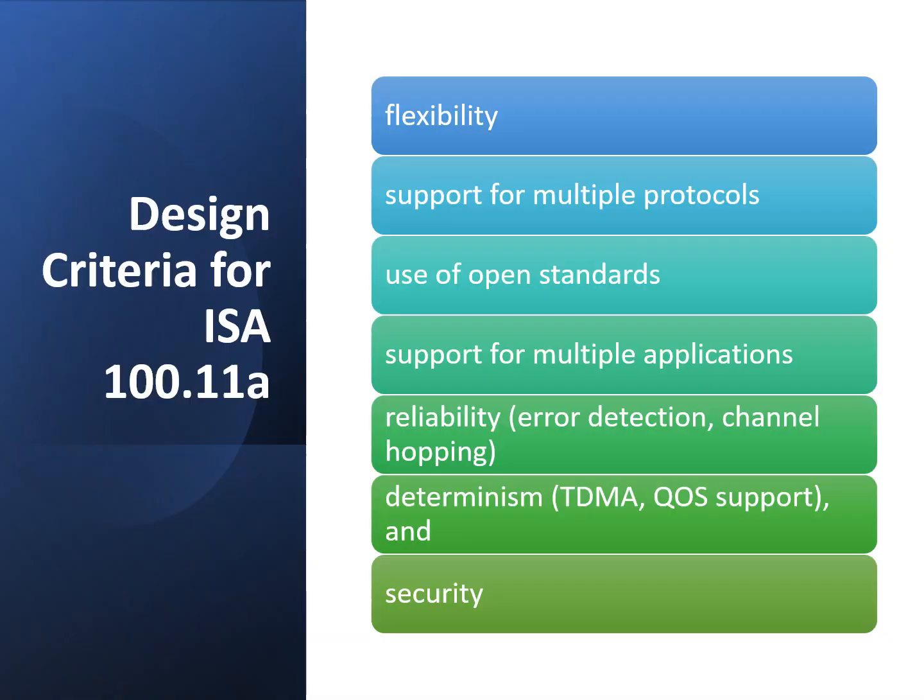The design criteria for ISA 100.11a include the following: flexibility, support for multiple protocols, use of open standards, support for multiple applications, reliability, including error detection and channel hopping, determinism, TDMA, QoS support, and security.